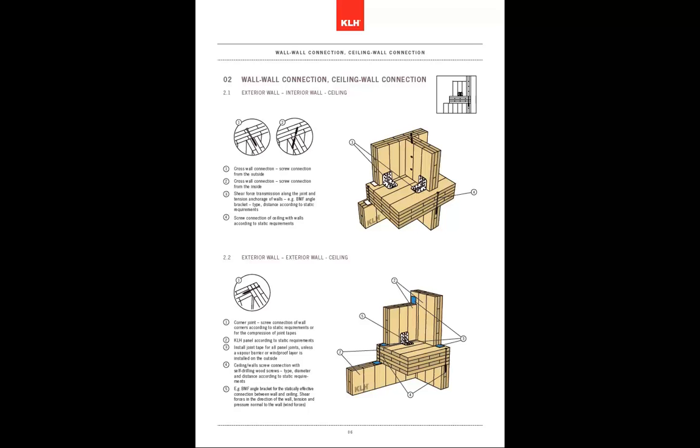It's amazing actually that you don't need to pre-drill them. You just get a powerful impact driver, and those big long screws, you just drive them into the product, and they cut their own hole as they drill in.